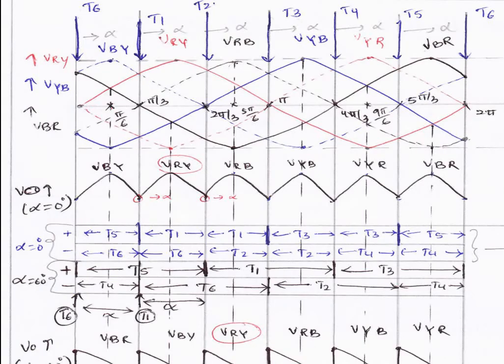So this could be your waveform. I will explain it neatly. First you draw the 3-phase waveform: R phase, Y phase and B phase. These are the 3 phases. Then invert these traces in order to get the line voltages. This is the inversion of R phase, and similarly the inversion of Y phase and B phase.